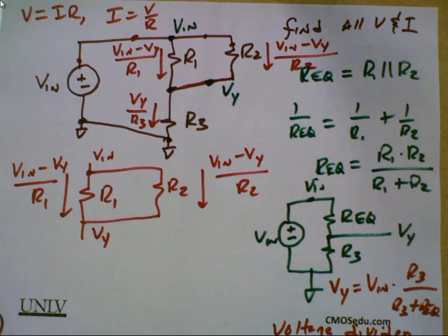It's like if I'm standing in a puddle and there's an appliance there, say a toaster, and the toaster heating element's on and drawing a current. I come up and touch it and provide another path. There'll still be current flowing through the toaster, but some will flow through me. It just splits and goes down.